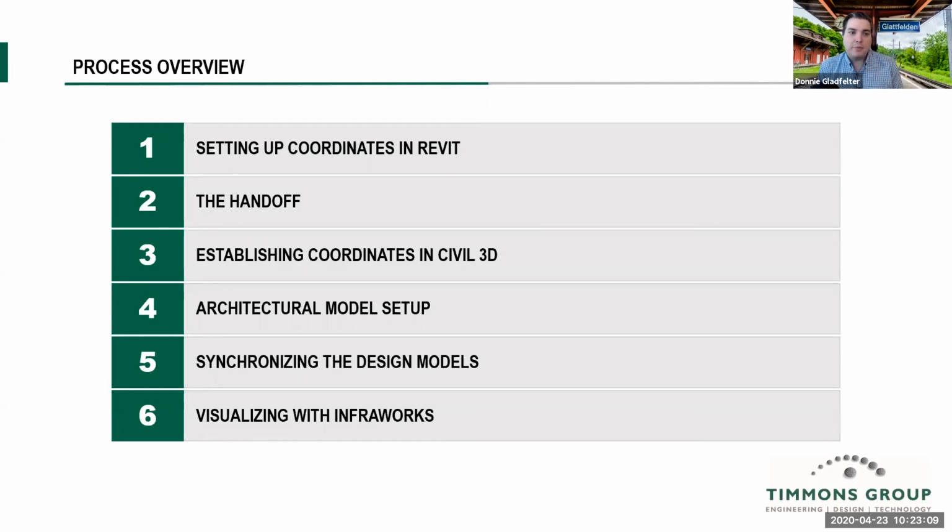Those are the two big things that we are going to model in 3D. I didn't show the pipe piece, but since that is in 3D and we can import and export things back and forth between Revit and Civil 3D, we can absolutely show that information. To get the site layout, since that is at elevation 0, I would just link the CAD file in. I would link, not import, so you could at least see the layout. It wouldn't be in 3D, but you could at least see it. So maybe I went a little beyond okay.